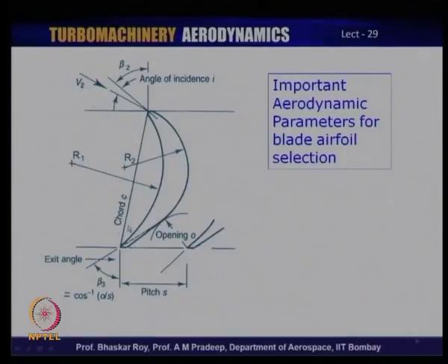And then of course, you have to decide fundamental aerofoil parameters, the chord of the aerofoil, which is the absolute value of the chord, and this is decided by a number of considerations.